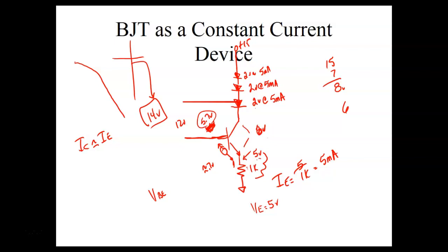NiCads have a discharge rate about the same as a lead acid battery. So that means if you have a lithium battery on your car, instead of your starter turning over slow, it just wouldn't turn over at all. So lithium batteries, you've got to be careful on those. Lithium batteries are unforgiving in that way, but they're a lot more forgiving than the NiCad batteries when charging. So you can leave those on a charger pretty much all the time.